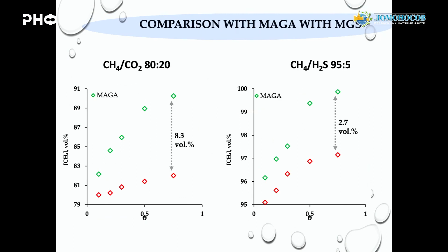By bubbling the mixture through the absorbent, we dissolve the CO2, and the methane, which has no absorption ability in this absorbent, goes out by pressure, and the absorbed CO2 goes through the membrane because of the pressure difference, because of course you need a driving force, and in our case it is the pressure difference or partial pressure change. This is the easy idea which we implement in this experimental setup. And we obtained nice results which are better in comparison with gas separation.